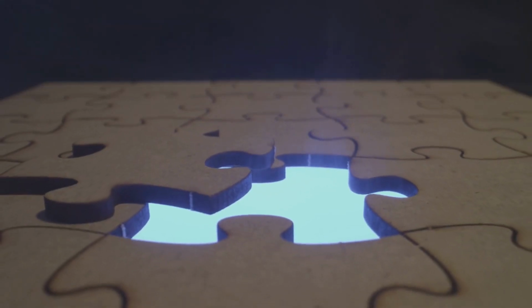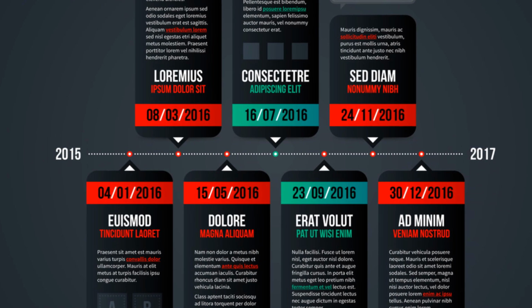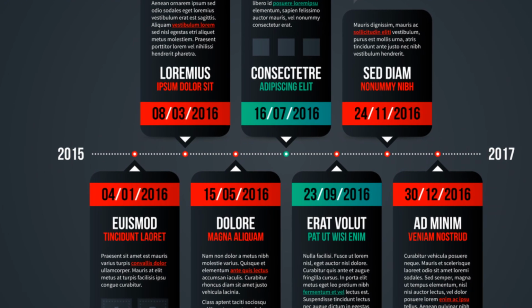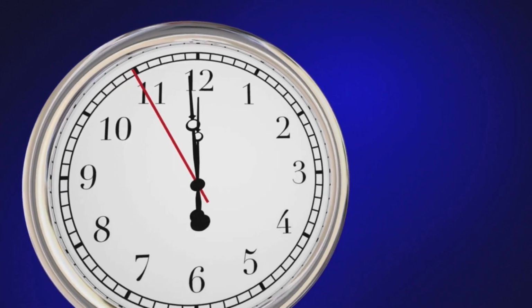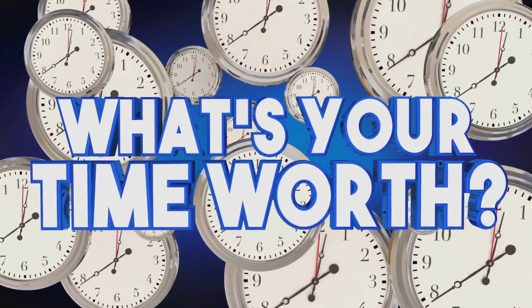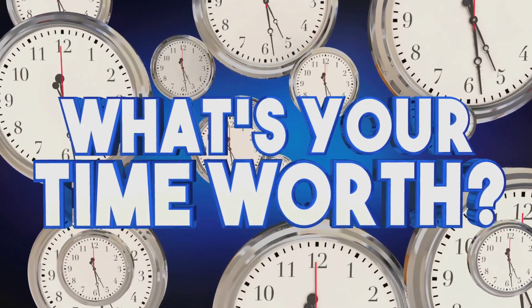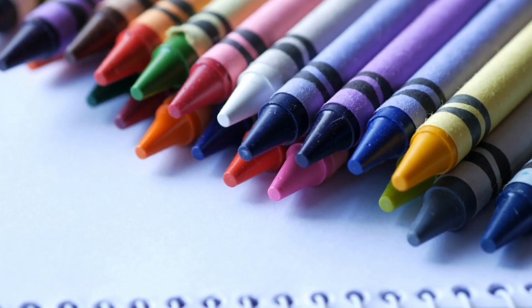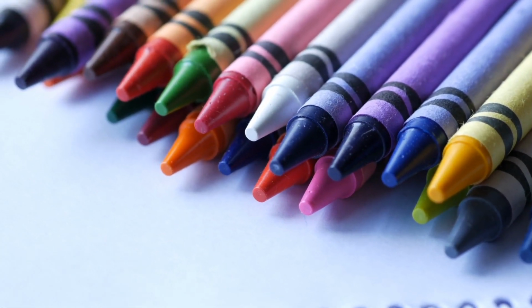The final step, adding a timeline to the bottom of the map. We add a timeline at the bottom, representing the total time it takes for a crayon to move through the entire process. On top, we log non-value added time, the time spent waiting, in transit, or in storage. This is time that doesn't directly contribute to the creation of the crayon. We see that crayons are waiting in inventory for 4 hours, a significant amount of non-value added time.